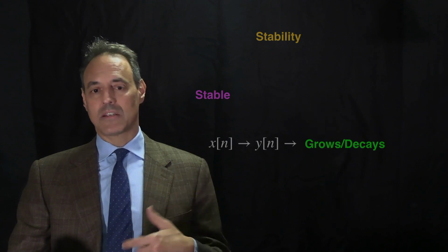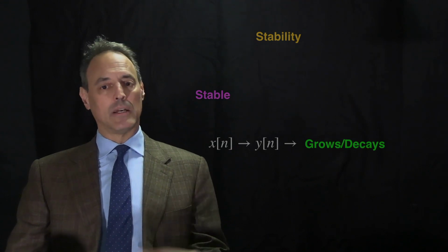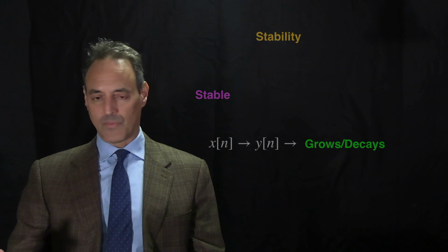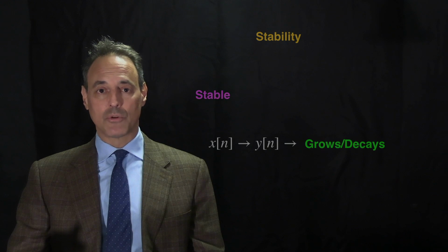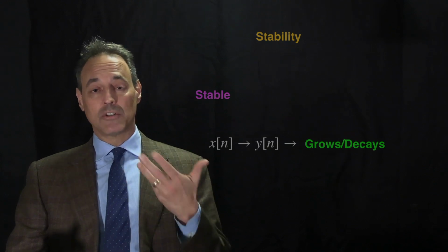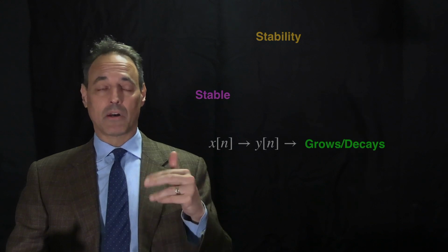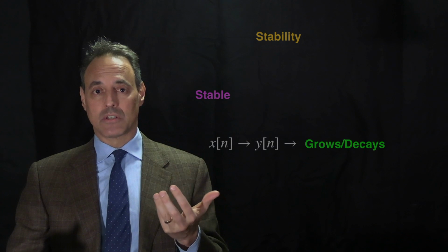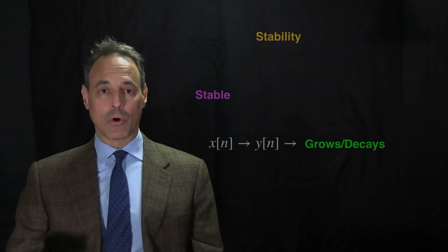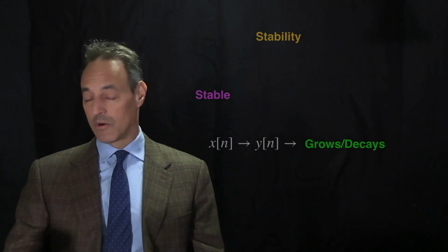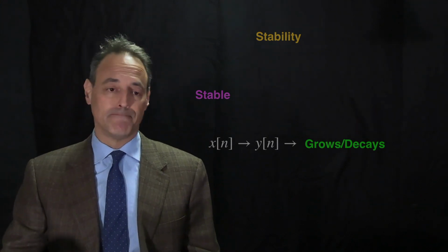However, if the state of the system is a quiescent state, zero state, and this thing decays down to that, then I'd say it is stable itself, okay? So we will formalize these relationships. Stability is going to come down to thinking about mostly linear systems, and in linear systems, it's all going to be about calculating the eigenvalues of that linear system and making sure that we don't have any exponentially growing solutions, which means eigenvalues that have a real part that are positive.